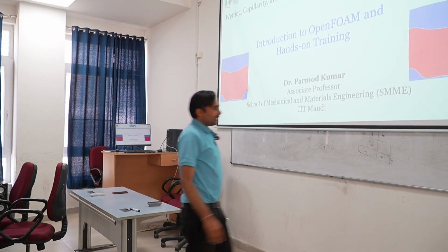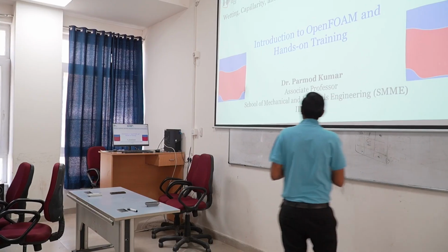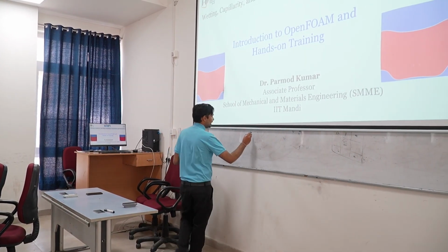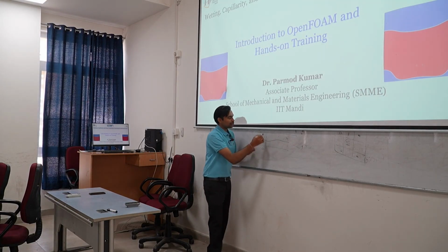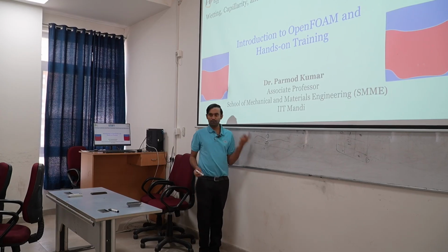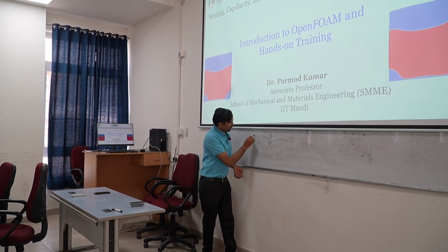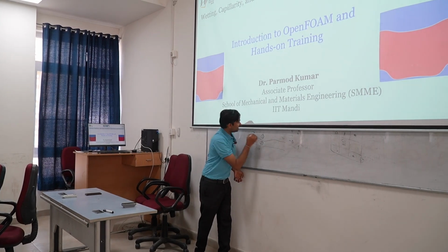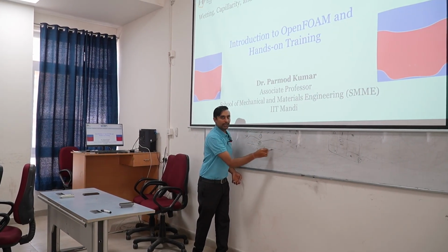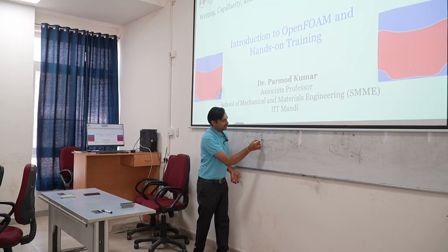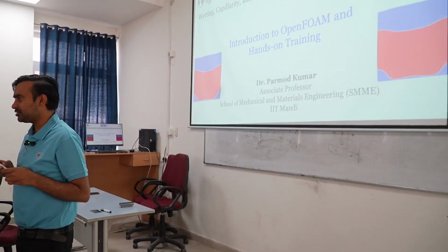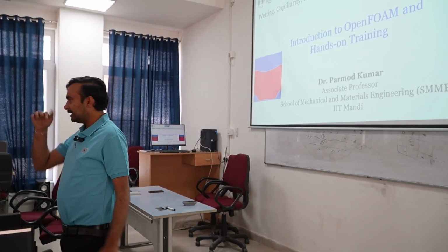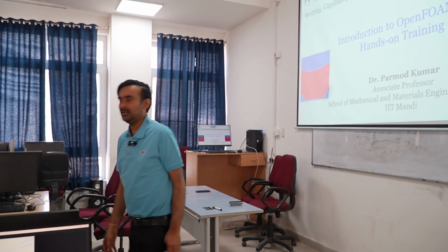Whereas in the case of multi-phase flow, or if two fluids are simultaneously flowing, then in the pipe I may have a portion of the tube filled with fluid 1 and a portion filled with fluid 2. So in addition to the boundary conditions at the inlet, outlet and at the pipe wall, we may also need to define boundary conditions for how forces and momentum are being exchanged between the fluids, typically at the interface profile.